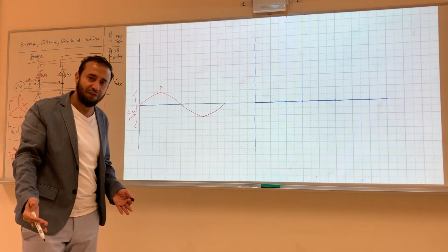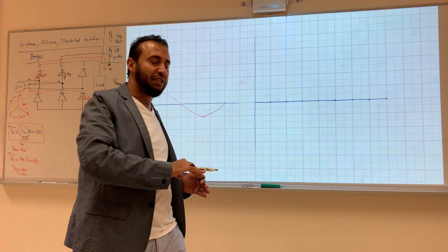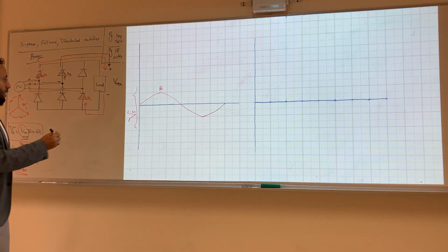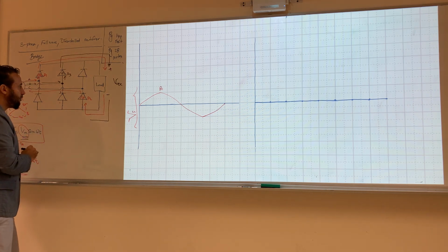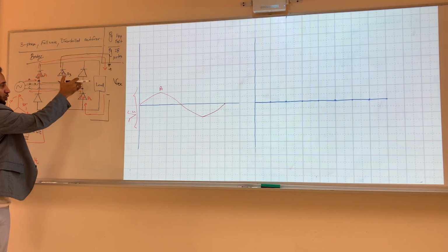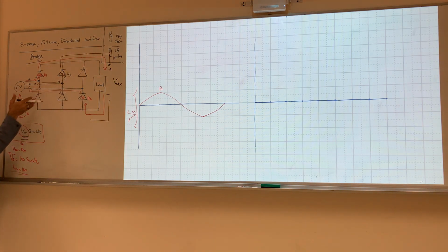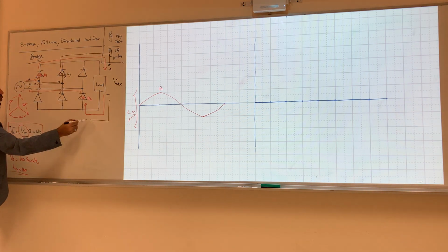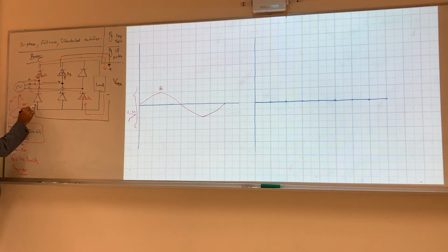And that's rectifying. We are directing the whole current to go to the load from the same direction, which is positive. Then it will go out. As we said, this polarity, because this is fully charged, will be an open circuit. So it will go either to this diode or to this one. And as we said, if we are in B, we cannot close with C, because C will start after this. So we have to close with A. And this one here is diode number 4. And then it closes right here.